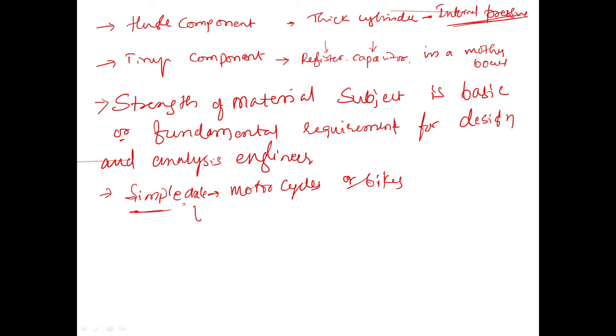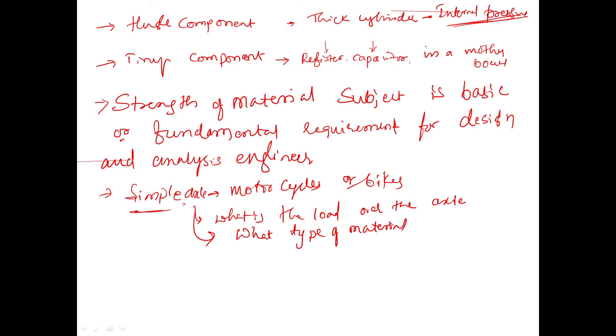You must know the load over the axle, what type of material you require, and what the induced stress is.